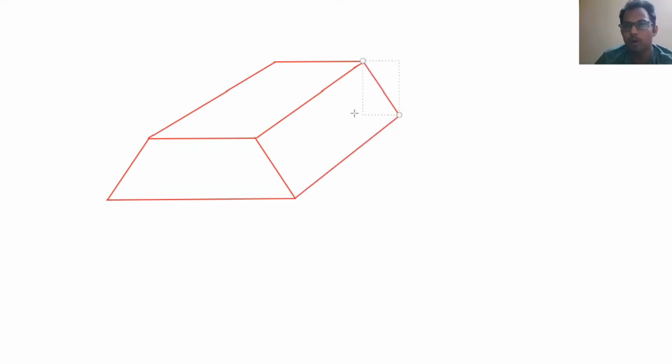If you want to determine the volume of this, you cannot use the long wall, short wall method or the centerline method here. What we generally do is take the height at different locations.